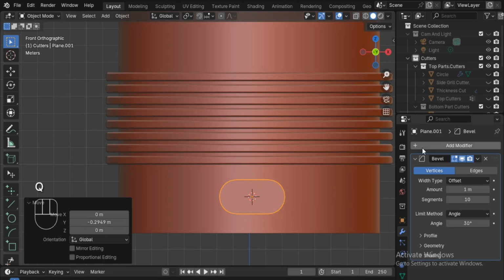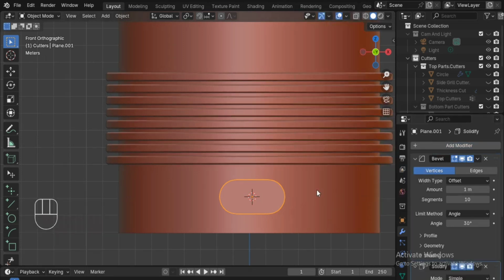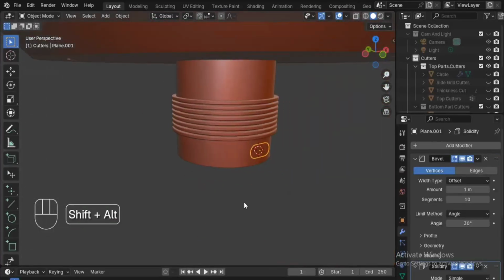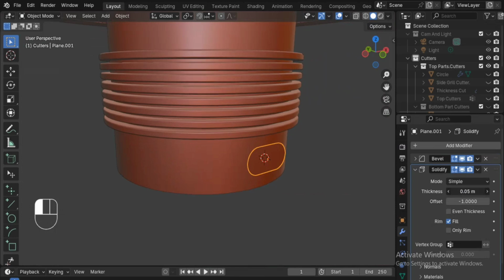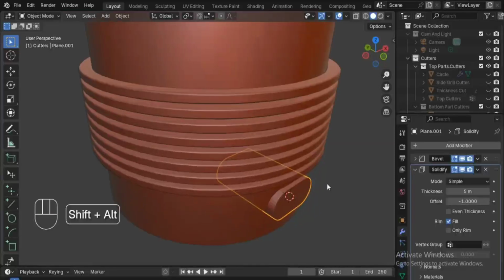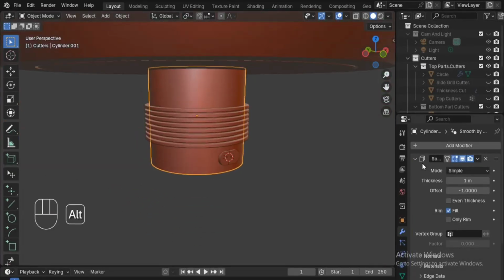And always use vertices if you're using a single plane with no thickness. And adjust the beveling amount. It's going to be round, so it's going to look like this. 1 for full round is what I saw the shape was like in the real world microphone, and the segments was 10. And add a solidify modifier to it.